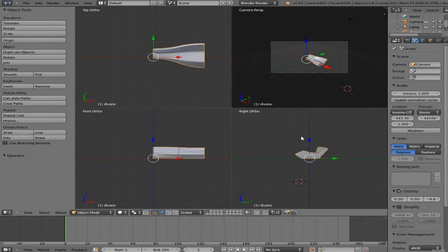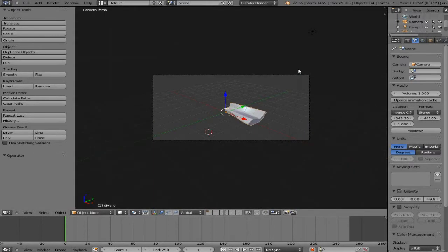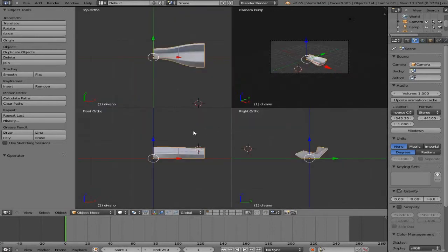Another one that's another toggle is called Toggle Quad View, and the hotkey for this is Control-Alt-Q. So when I toggle Quad View, it actually brings up 4 viewports in this one 3D view. So in the top right we have a perspective view, then we have orthographic or drafting view, so we have a top, front, and right view. This can be very helpful when you're modeling and you need to get very precise views of your scene. Again, this is a true toggle, so if I hit Control-Alt-Q, it will bring it back.